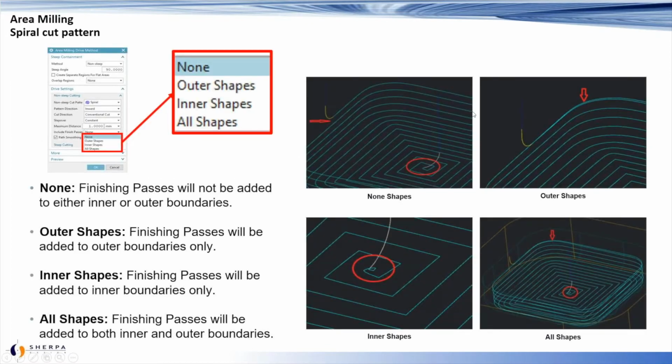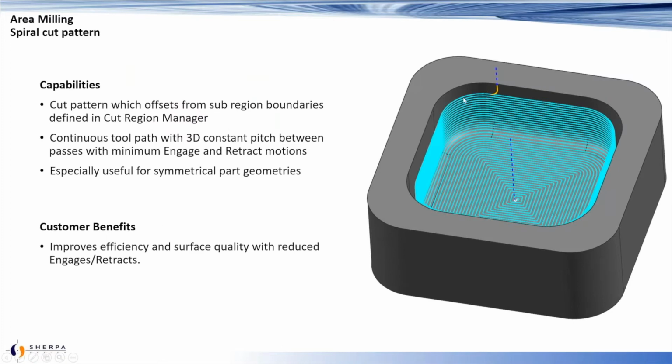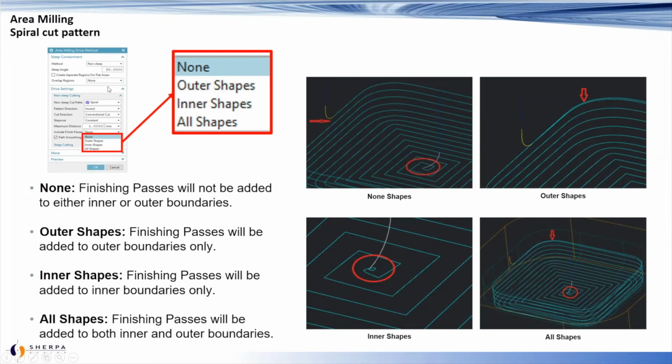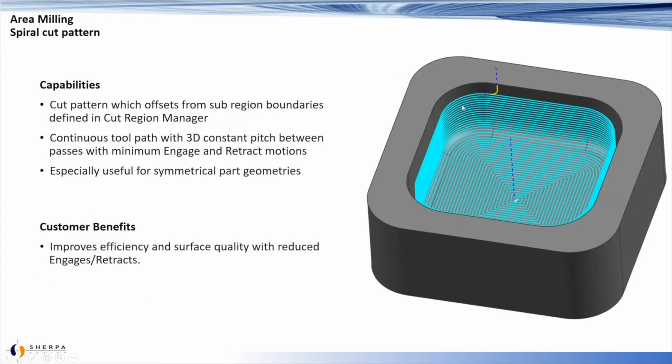One thing to note is for helical, the first time around the profile, if it's doing a helical on a steep, it could potentially be a lot heavier at the end of that perimeter on that first pass. And so they added finish passes, and you can put a finish pass on the top or on the outer shape. In this case, it would be on the top and then on the inner.